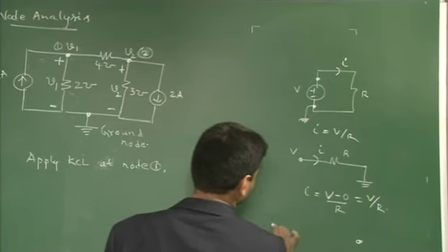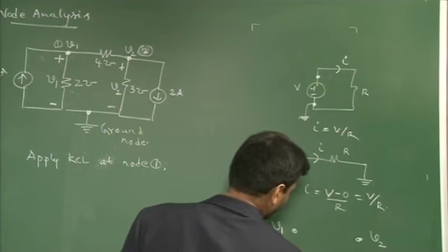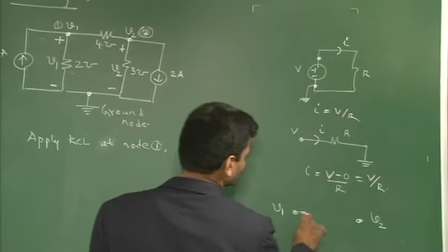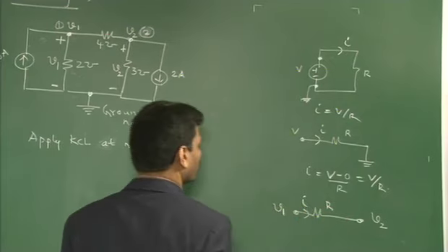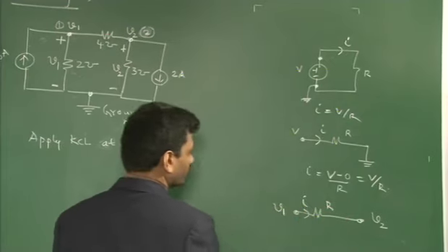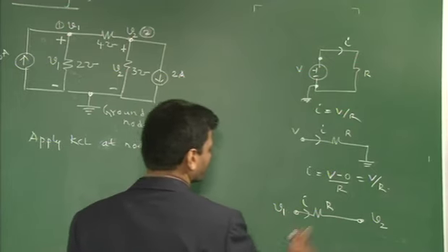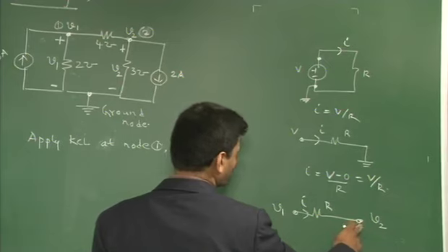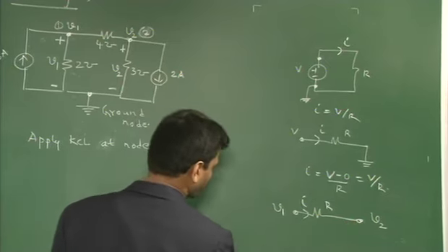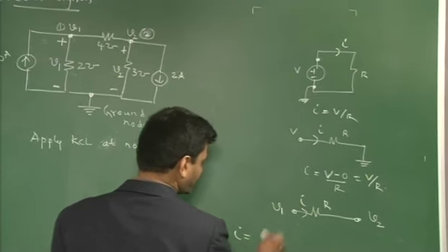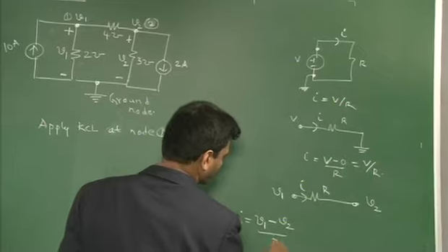Now, in the case of 2 nodes having the potentials of V1 and V2 with respect to ground, if I have to find the current I through R, what is this V1? V1 is the potential difference between this point and this point with this as reference. The other potential whatever you are identifying should also be with respect to the same reference, that we have to keep in mind. So, I in this case again is given as V1 minus V2 by R.